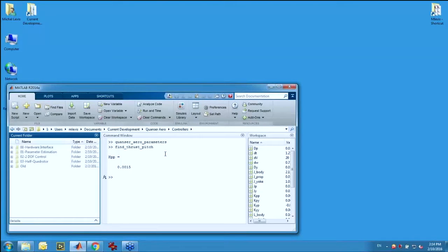As you can see, there's an Allen key that locks into place using these magnets. With this Allen key, I can choose to lock the yaw. If I put the Allen key in here, it fits through this, and then it locks into a little magnet here. You can't really see it on the camera, but in this little hub there's a magnet that couples to the Allen key that I've pressed down onto the unit. Now you can see that it's locked into the yaw. So the yaw axis is totally locked, and I can conduct pitch-only exercises.